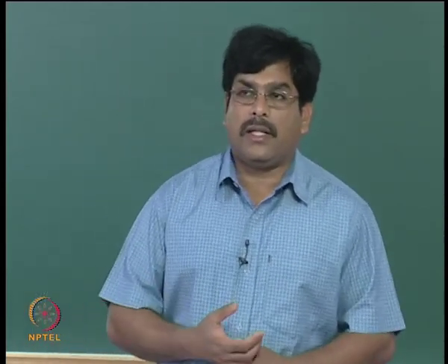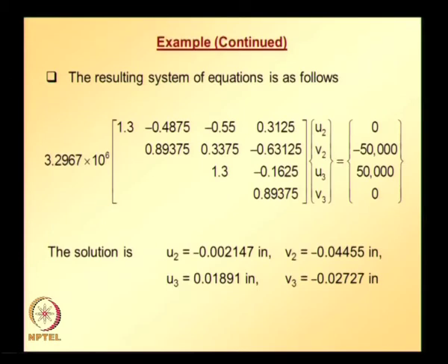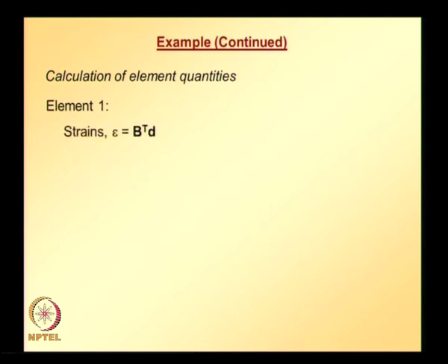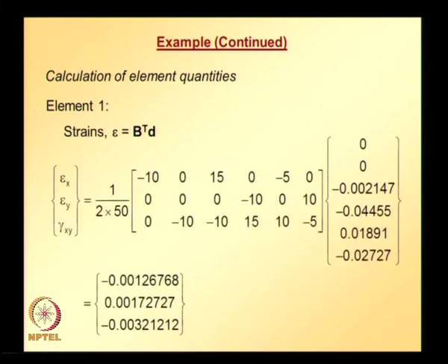Again, the solution is given in FPS units, but procedure wise it is not going to be anything different. And now that we got the displacements, we can easily calculate element quantities corresponding to element 1, strains and then stresses. Strains can be obtained using this relation, and please note that strains are going to be constant over the entire element, and once we got strains we can calculate stresses